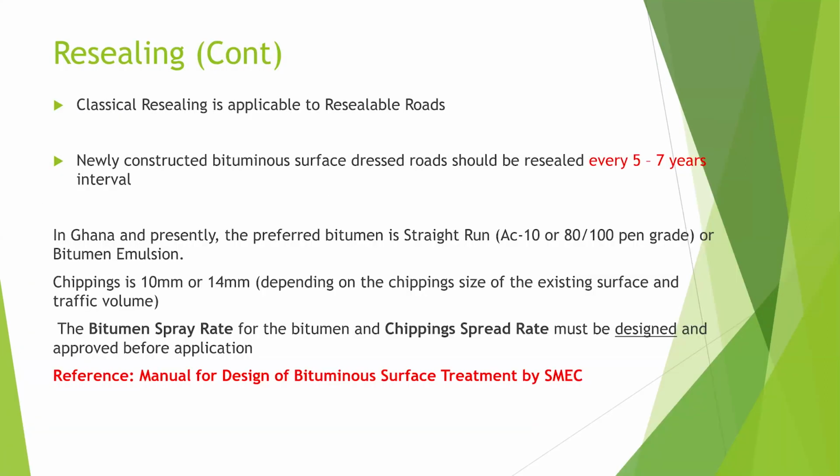Now, like I said, a classical resealing is supposed to be applicable to only resealable roads. If the road is not resealable, it means resealing is not applicable. When you construct a road, we should have a program, maybe every 5-7 years, to reseal the road to rejuvenate the pavement surface condition and the structural integrity.